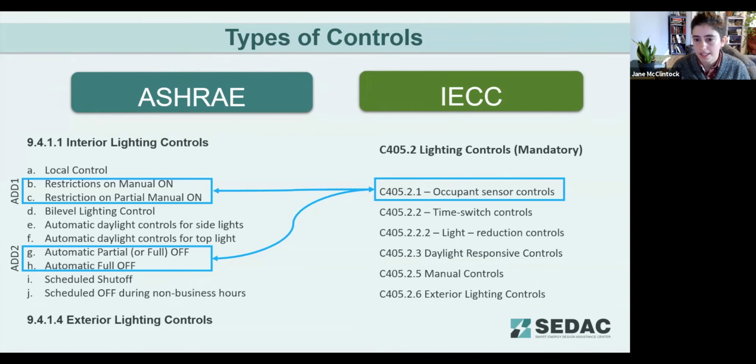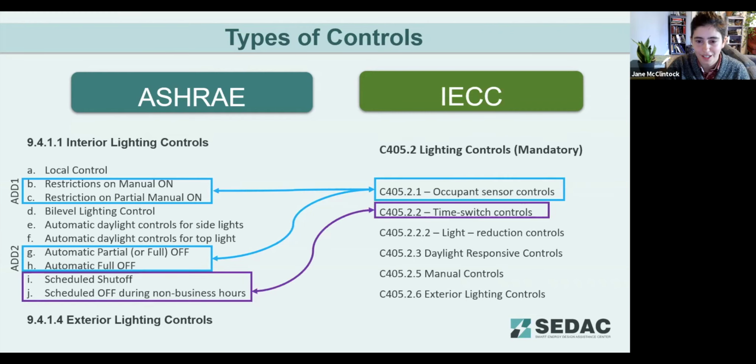So in IECC, the occupant sensor controls incorporate a lot of the aspects of these separate controls that we see in the ASHRAE tables. And hopefully that didn't make that more confusing. So next we have an easier one to link up, which is time switch controls. These are covered by ASHRAE's scheduled shutoff and scheduled shutoff during non-business hours. These are all covered under the IECC's time switch controls and the description of what those time switches need to do.